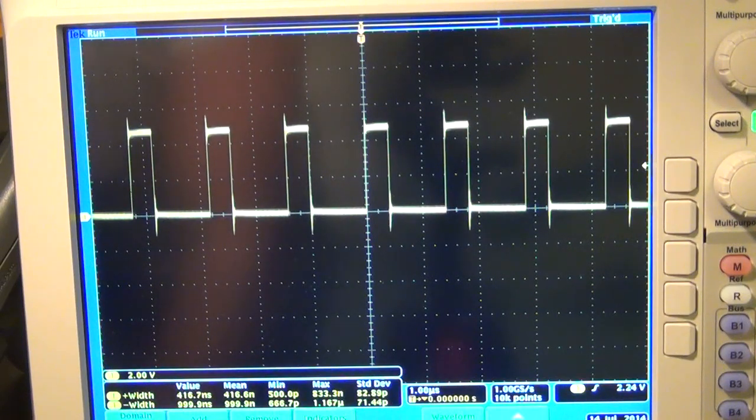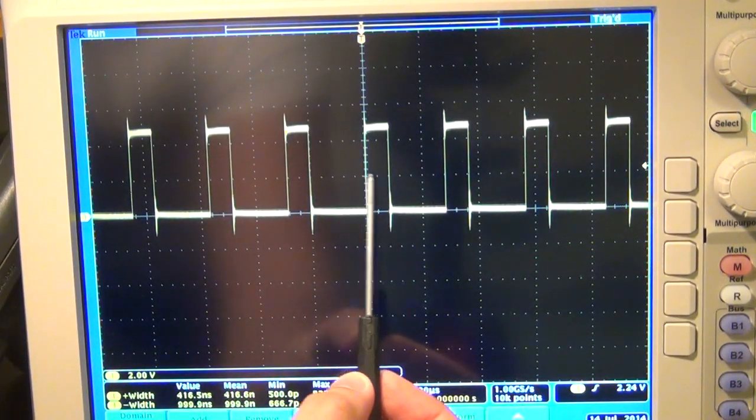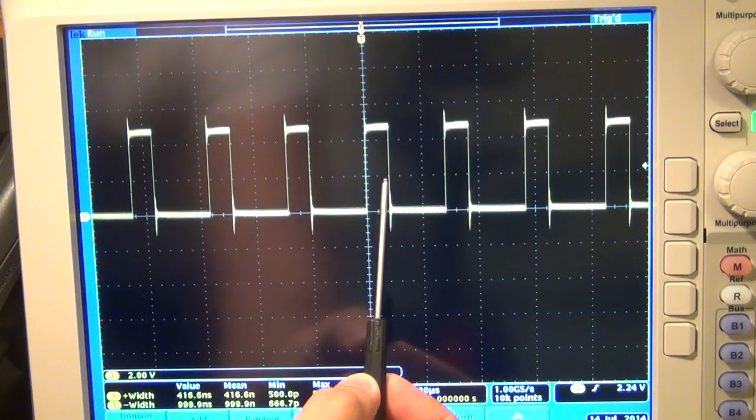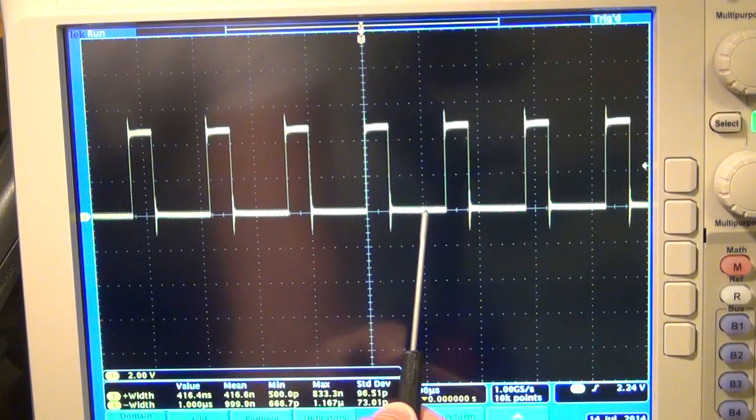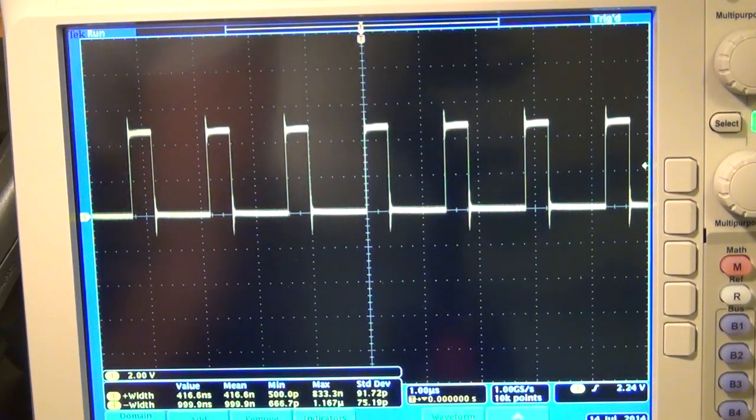But here's the really weird part. It still works. I'm not exactly sure why. I don't know why, even though I'm not meeting the exact timing requirements, I can still program the LEDs fine. I suspect what is important really is only the width of the first part of the cycle and not the second one. If you meet the first width and the second one is roughly close, it will still execute it for you and it will still accept that as either a 1 or a 0.